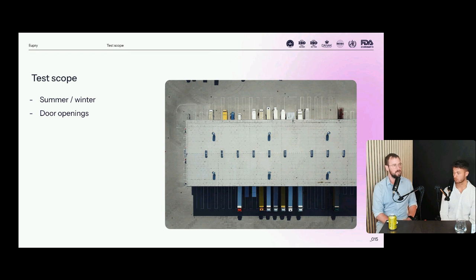One of the examples we often see where auditors are not really satisfied is that the door opening studies that were performed were not based on expected usage of the equipment or actual usage of the equipment. So again, you need to identify what is my risk. Well, if we're opening up this freezer 20 times a day and it's for 30 seconds at a time, your testing scope should cover that. Otherwise, you can't mitigate that risk.